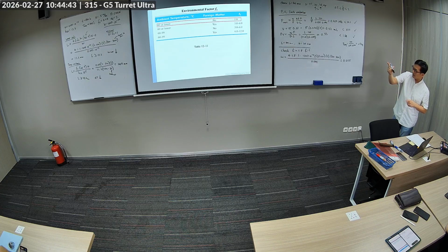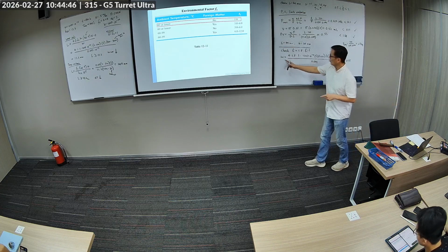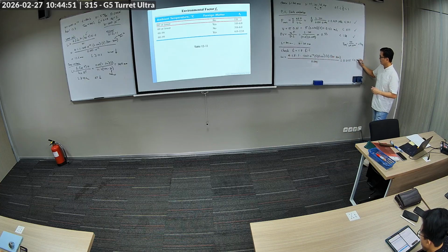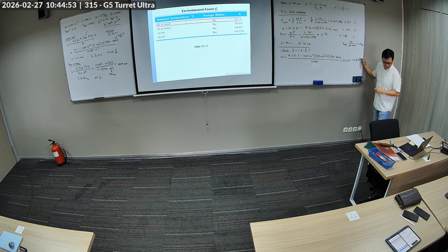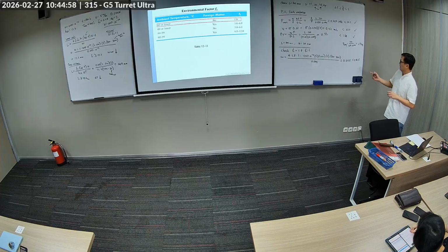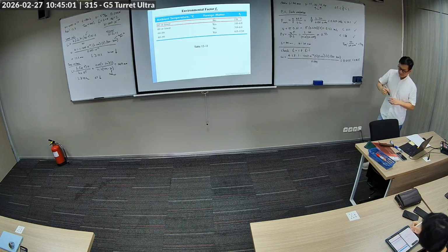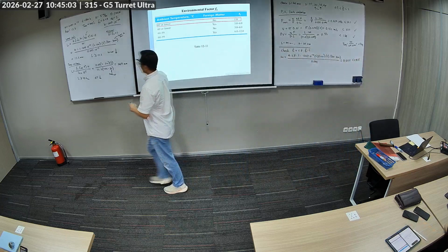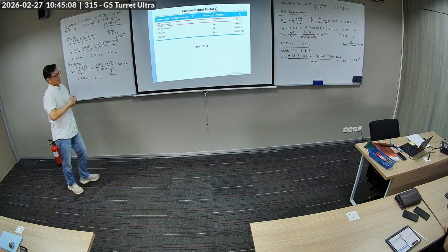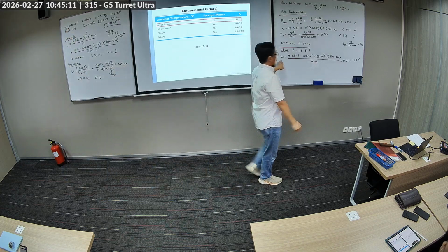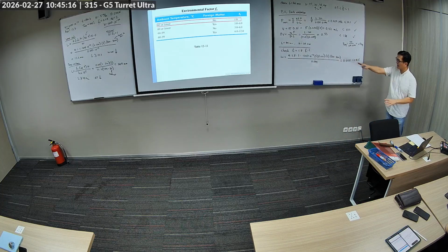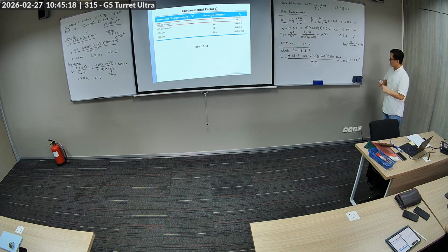What is W there? This is the W with this parameter. This is less than the limit. Okay, the limit was 0.025, and this is less than that. Okay, this is the wear limit. So our actual wear after we select the size and everything else is still less than that, so this is okay.